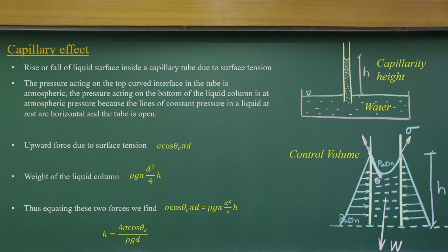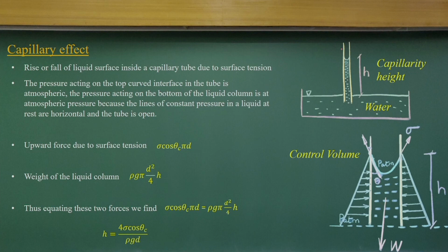As you may have seen in some books, even at class 12th level, we just sum two force components: the force due to surface tension and the gravity force of the capillary part. You know what capillary is? If you insert a small tube into a fluid, you can see a rise of water or a fall of mercury, and that height is called the capillarity height. Here we have water and a small glass tube; if you insert it, you can visualize that the water will go into it. This is the capillary effect.